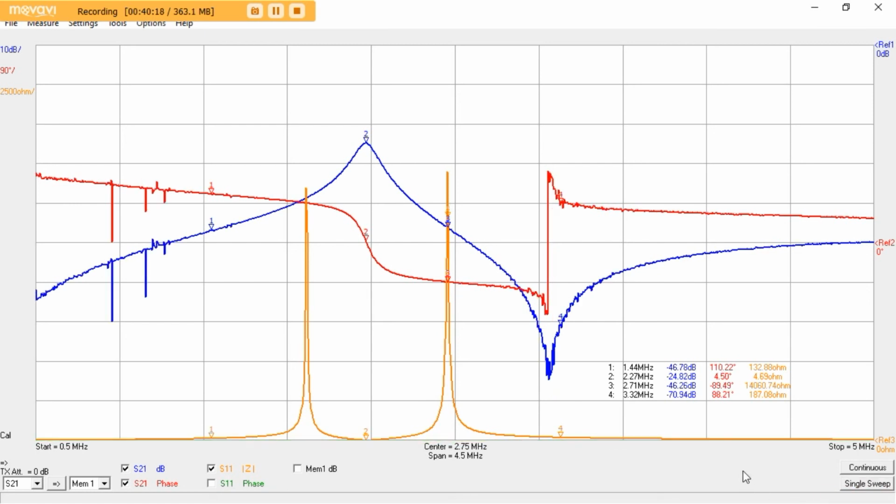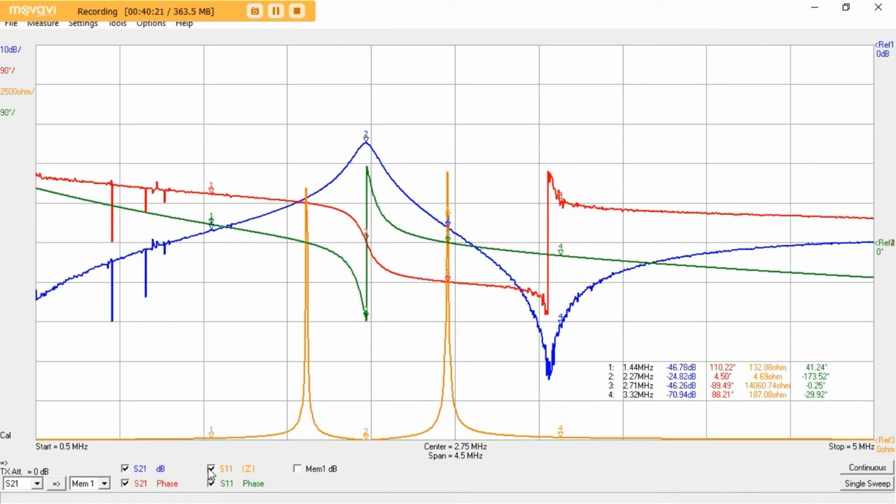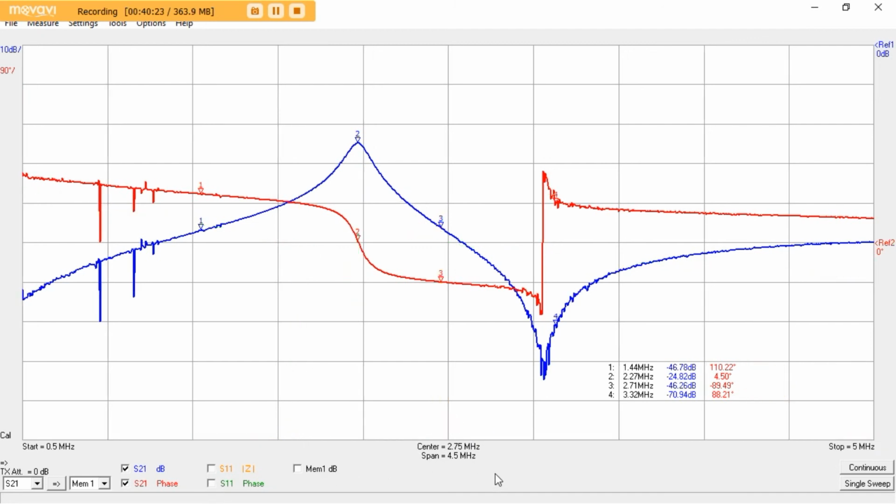Good. And that is the S21, the transmission gain of a cylindrical Tesla coil with characteristics as I've shown, and I'll be looking at some of those results in more detail in the write-up. And as I said before, the next part of this will be to extend that transmission gain over to a full TMT system with a transmitter, a receiver, and a single wire in between. Great, that's that for this part.